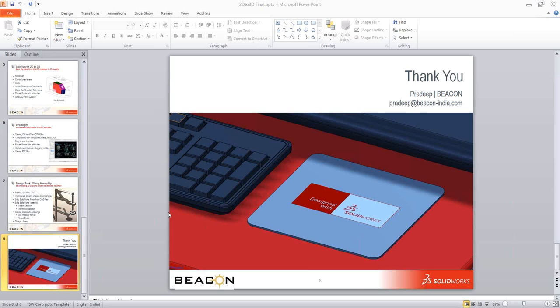I have one more question regarding a section view. It really depends on what you're trying to use. See, if it's a revolved component, you saw me using that section view for a revolved component. Yes, we can definitely use it. Again, it really depends on what kind of section view it is and what you're trying to build out of it. So my simple way of answering your question is yes, we can use section views to convert 2D to 3D. We did that with the second part. If you remember, we brought in a section view, and it's even easier to create a revolved component using a section view than the glass box method.